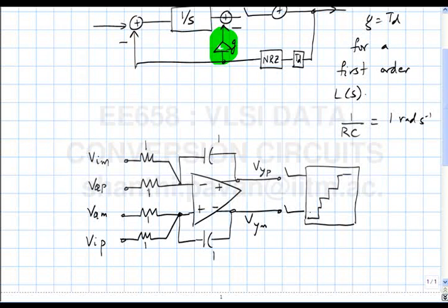Please note that by Thevenin's theorem, applying a voltage here through a resistor is equivalent to pushing a current directly into the virtual ground of the op-amp, in shunt with a resistor. That resistor will be between ground and the virtual ground of the op-amp, which means that I don't have to have it in the first place. You understand?